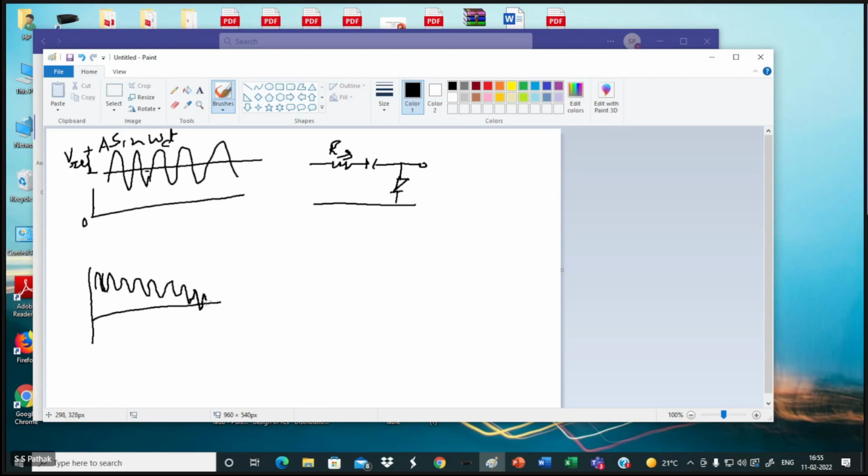Now it becomes 0, and it will be like that. Or, some small tip if you want, you can add it there according to the numerical question, if the capacitor value is not sufficiently large, etc. So that's how it is coming, and now it is clamped.